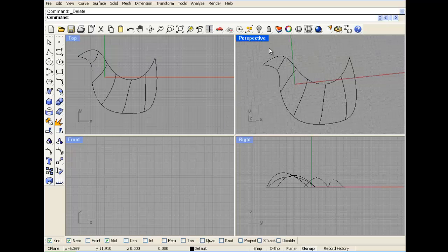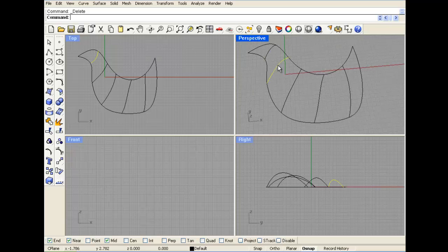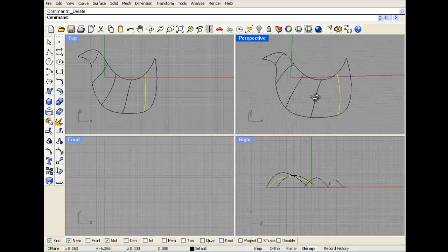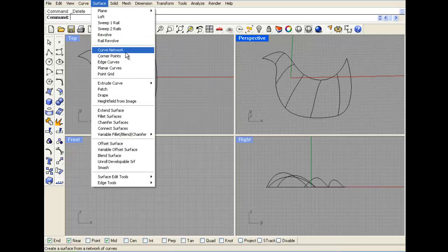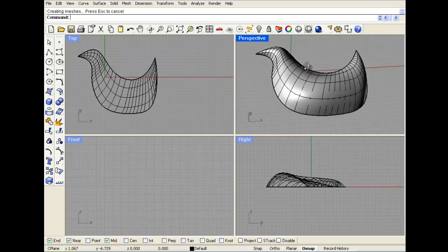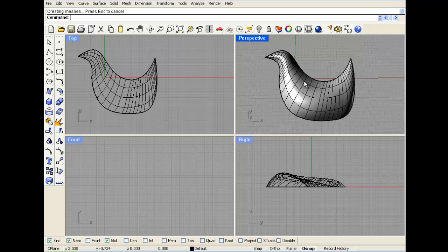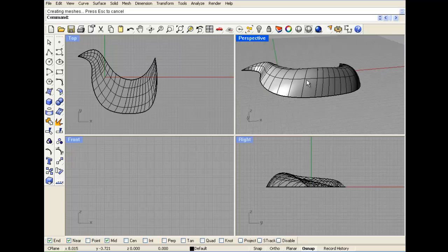I would like to delete this and show you what I'm talking about. So sweep to rail says there's a rail going this way and a rail going that way, and your inputs count. But if I wanted to adjust the spine, I need to come here and adjust this one, this one, this one, this one, this one, to get a taller or shallower surface. So let me do Curve Network again. And two commands that I'm a very big fan of today and typically always are duplicate edge and extract isocurve.